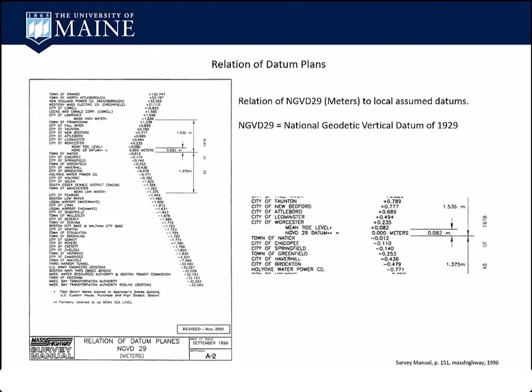The other thing is, as you look at this, at the bottom, there's the MBTA, the Mass Bay Transportation Authority, Mass Water Resources. They got these datums that are 32 meters below what was originally sea level. Why would they do that? Well, it's because they have tunnels and they want to work in positive elevations.